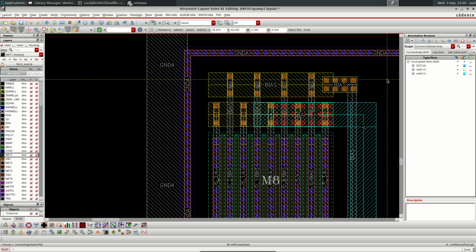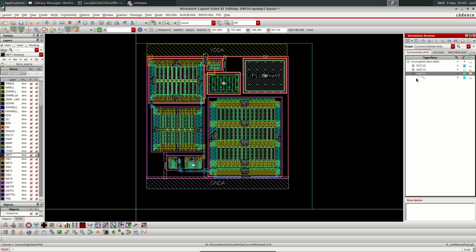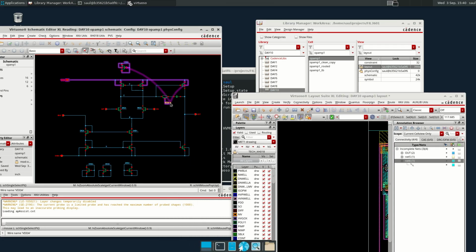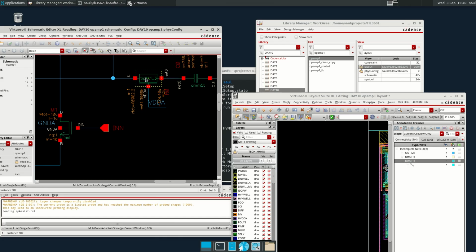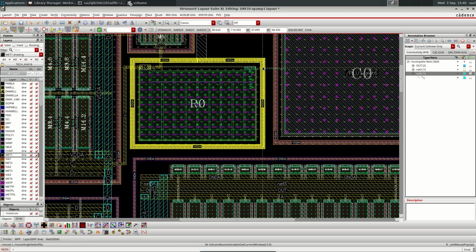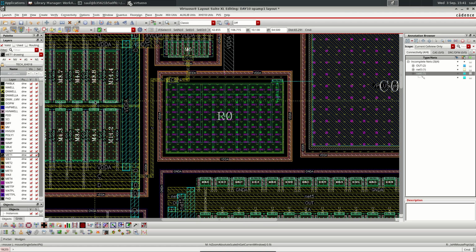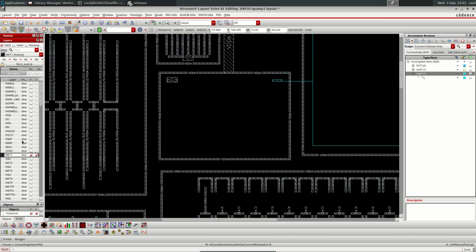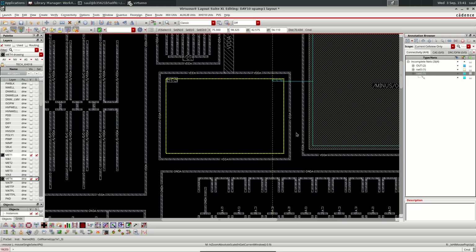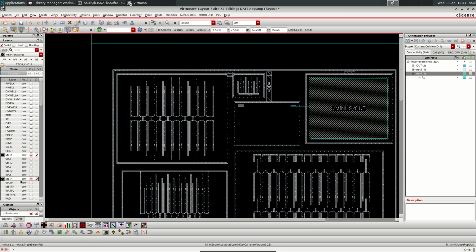And there are only 3 nets that need to be laid out before we finish. Net 6, what is net 6? Net 6 is this connection between the resistor and the capacitor. So it is telling me this one here. So let's see here. The output is connected in metal 4, and the plus is connected in metal top.